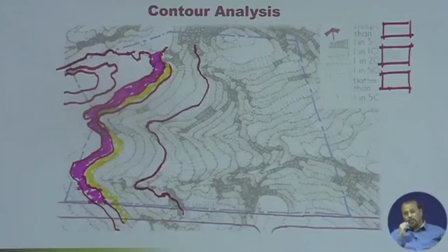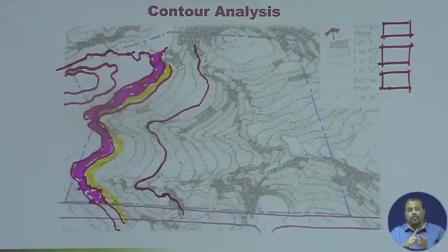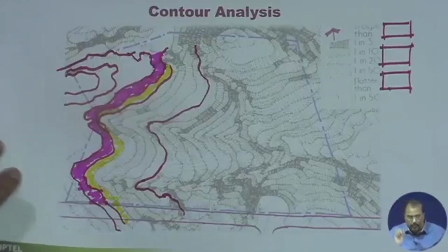Few things you have to keep in mind. Technically, contour lines generally don't cross each other. When I say generally, there must be some exceptions. If they do cross, then either it corresponds to the levels changing and entering into the others, or else there is a mistake in the drawing. I will clarify that particular point a little more. It is important to be understood.